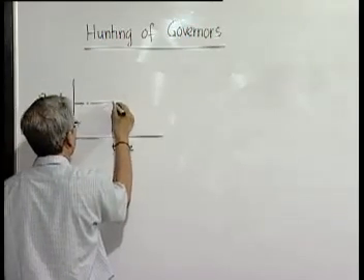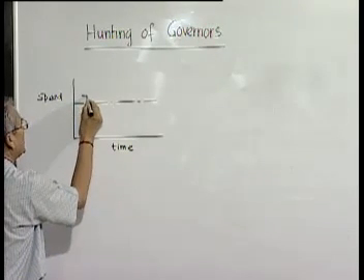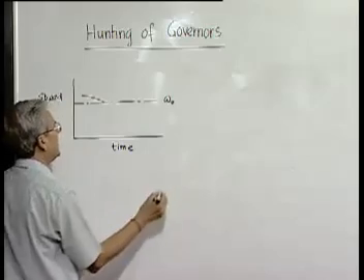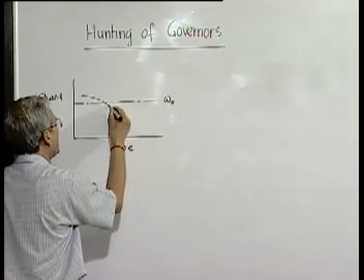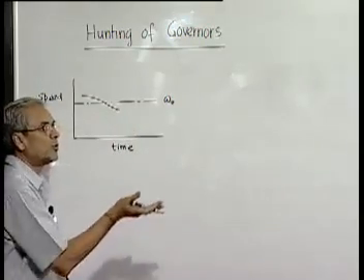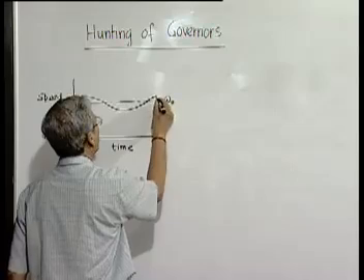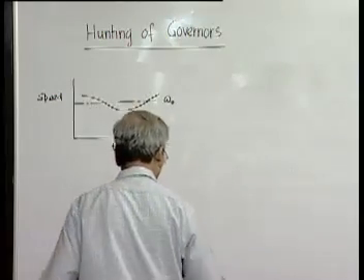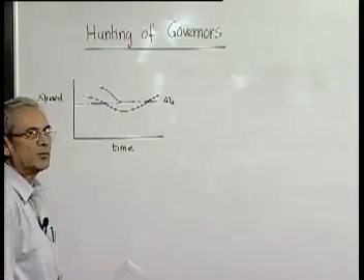So this is our required speed, and we are somehow here. So what we do, we try cutting down the input so that speed reduces. When it comes here to our desired operational speed, it does not stop here because the whole system will have some inertia. So it continues, it goes below the desired speed, but again, since it has now become less than the desired speed, input will be increased, and then again slowly it will try to come here. Again, due to inertia, it will overshoot, and this will cause the whole system to hunt. It will not asymptotically stop. The ideal situation would have been that we start here and then reach this, but that will not happen.